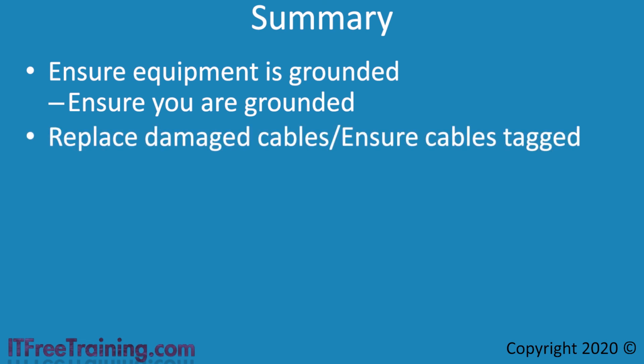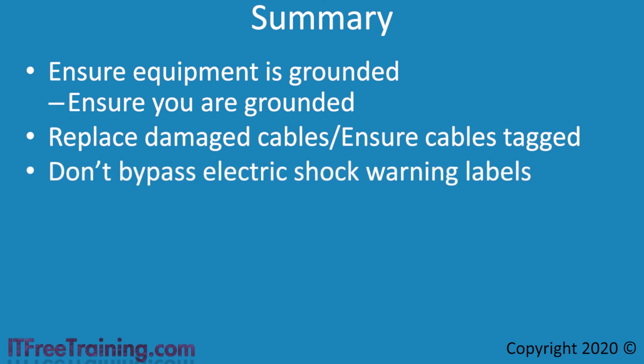Replace any damaged cables and ensure that they are tagged. Different countries will have different regulations on how often the cables need to be tagged. This can also vary depending on where the cable is being used. Do not bypass electrical shock warning labels unless you are trained to do so. Some devices hold a lot of charge. Opening the device and touching the wrong part may give you an electric shock. Remember, electric shock can cause muscle spasms, burns, and in some cases, death.